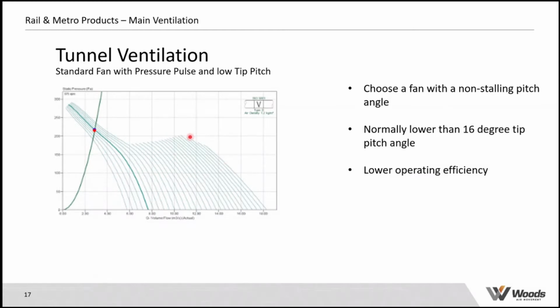So for axial fans, where I'm showing the red dot now generally represents peak efficiency. Around two-thirds up the curve and two-thirds into the pitch angle range is generally peak efficiency, and it's a bit like a bullseye or a circle that comes out from that, and the efficiency gets lower and lower as you move out. But again, it's more important that the fans operate and are safe to operate, and there's a slight trade-off in terms of lower efficiency.